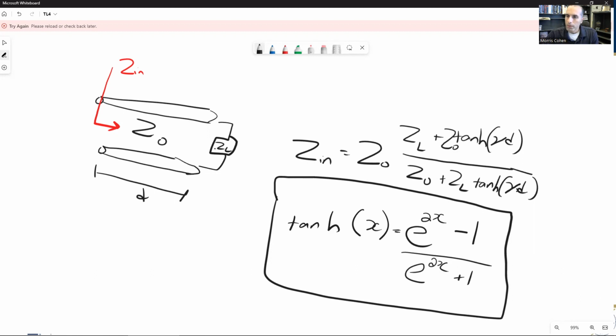Long story short, if we have a lot of attenuation, we're going to attenuate the signal. If we consider Zin, the original definition was the input voltage plus the output voltage divided by the input current plus the output current. What's going to happen if we add attenuation is that these two terms will shrink.